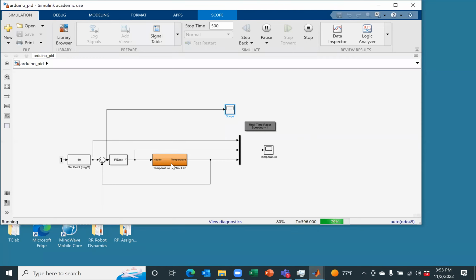That is how I did it. But there are guidelines on how to tune the PID controls, and this actually worked for me. First, control the P, make sure the system overshoot is reasonable. You cannot eliminate overshoot. System will have some overshoot. Steady state error is reasonable.